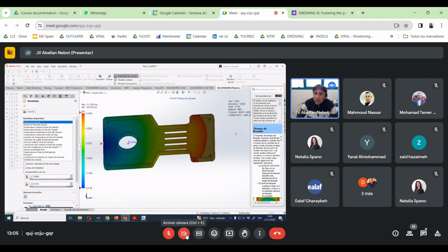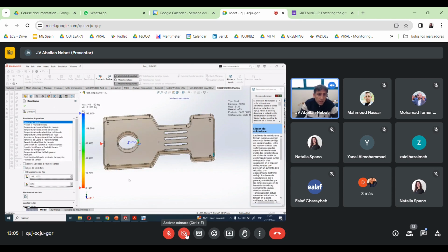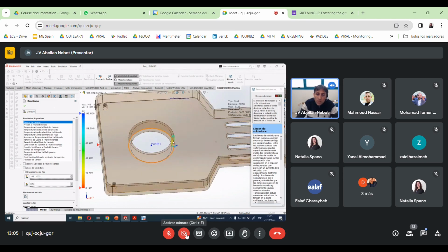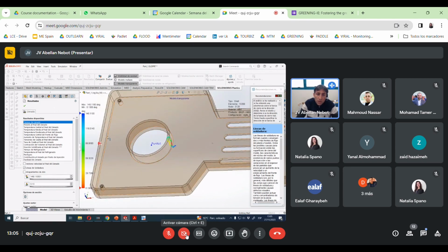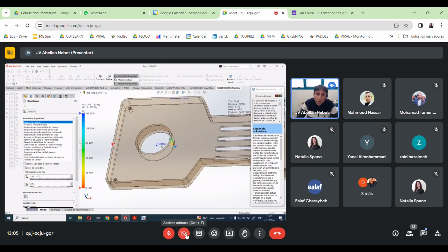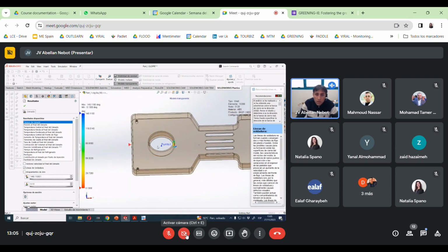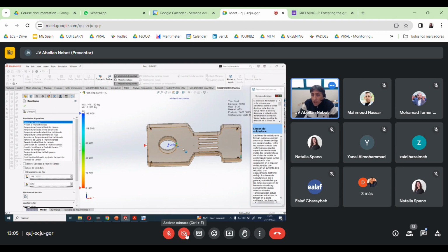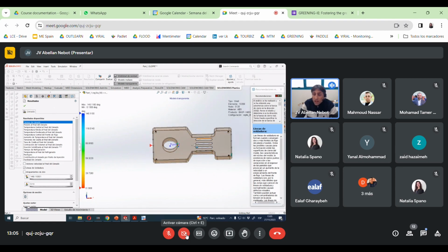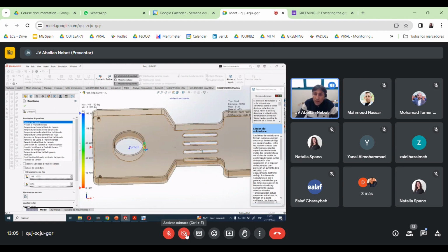So it's going to that part, and we can see the welding lines. You see, there is no welding lines here. The only welding line that we have is here because the flow front splits in two, and then there is a collision of the flow fronts here. So this is the welding line that we have. It's normal because it's a hole. There is nothing that we can do. But here we don't have any welding line in this grid. That happens in the previous design.